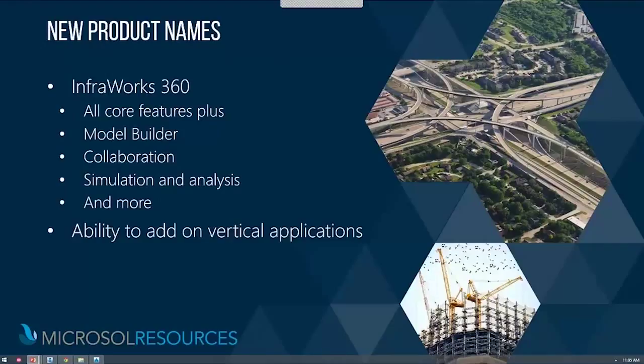But on top of all the InfraWorks 360 LT features, you get a few more things, namely the access to Model Builder. Model Builder being one of InfraWorks 360's probably the most powerful features. It allows you to aggregate data pretty much from anywhere in the world these days. I'll show you the limits of where you can access data, and it'll pull in geospatial information files based on terrain data, based on ortho imagery, based on roads, buildings, bodies of water, et cetera. So extremely powerful for getting up and running with the concept without too much effort on your part.